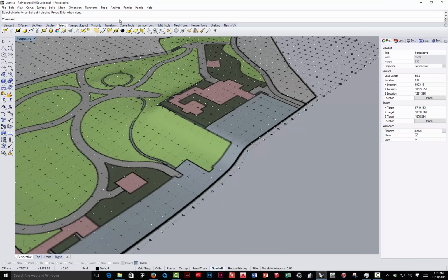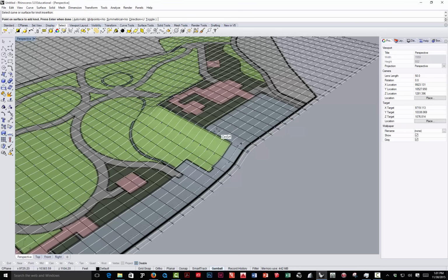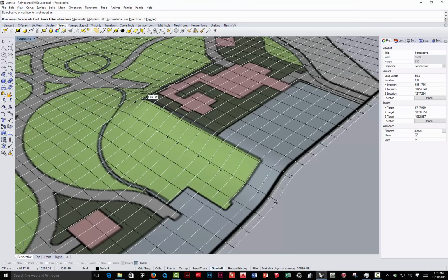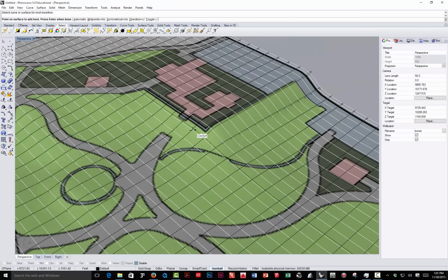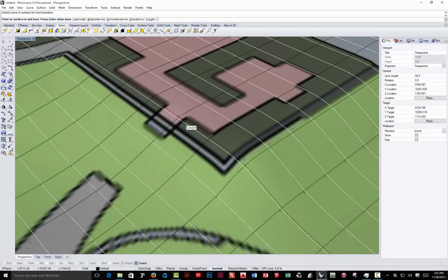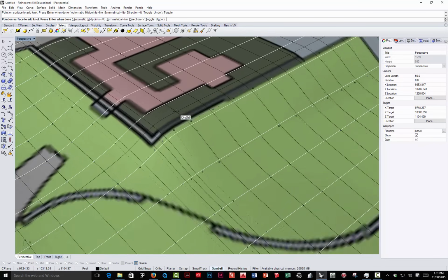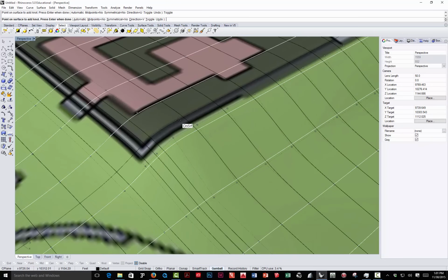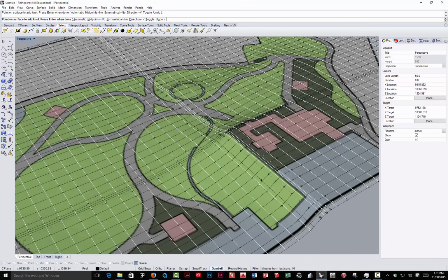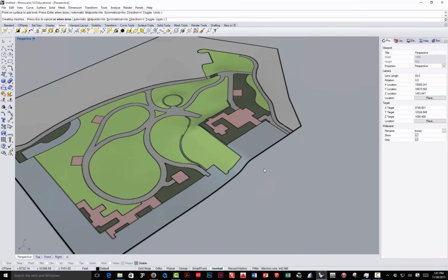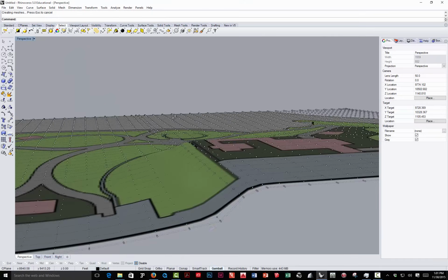So you can actually do that pretty easily if you use the Insert Knot command. So I'm going to select the surface, and you can see it's giving me an ISO line, a control point line that goes all the way across. So I'm going to set one right here, and I'm going to set one right here kind of inside. And then I can go up and just say toggle, and now it's giving me the other direction. So I'm going to set one on my inside there. Set one just on the inside there. And I think for now, I'm going to right click and adjust that.